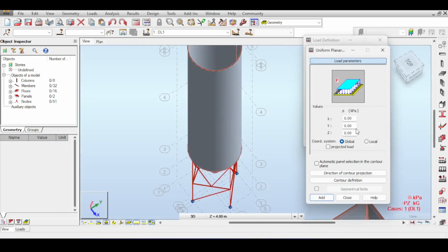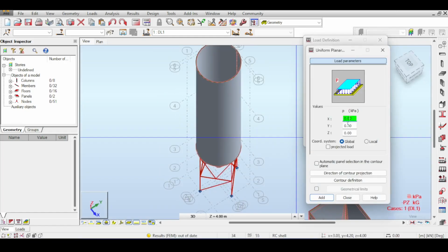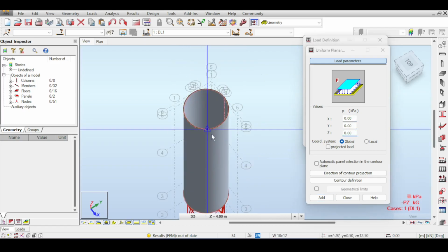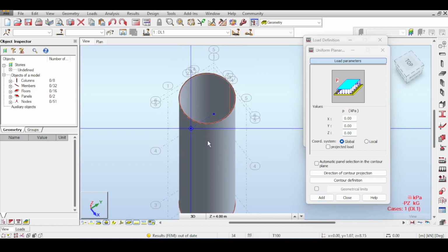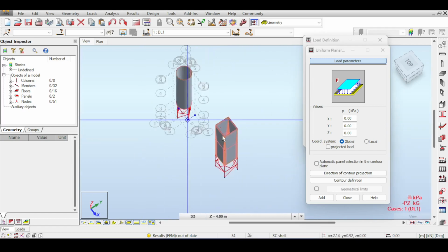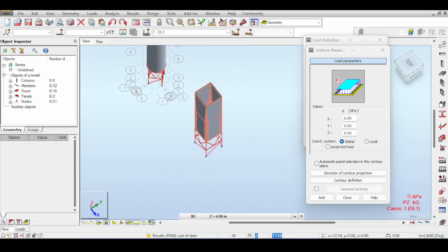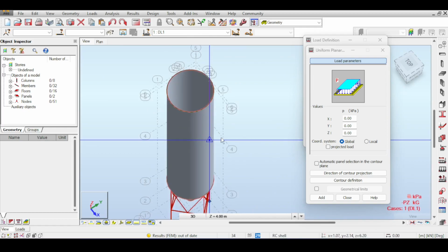If you click on contour, it won't work because you see the X is global and you have a curvature here, so the global doesn't work because the curvature keeps curving around the element. So what works in X for this point doesn't work here because here you need a Y. I mean, remember what we did here, right? In one point it was an X and the other point was a Y. The curvature makes it even worse.